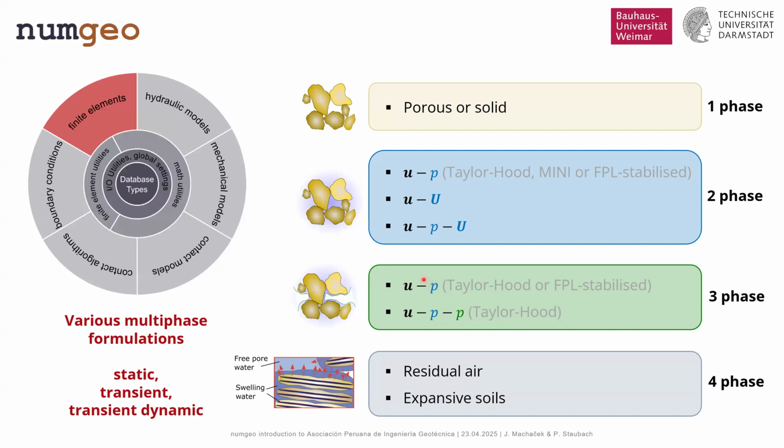So for most geotechnical practical applications, the UP formulation, the simplified modeling approach here, is just well enough. Based on these formulations, we also developed extensions and new equations that better describe the physics of soils that have a residual air and also of expansive soils. This clearly falls in the range of research, but was also performed in the framework of NUMGEO.